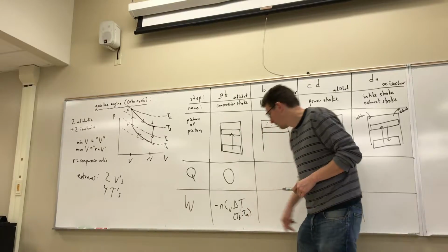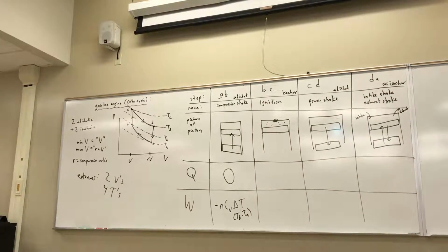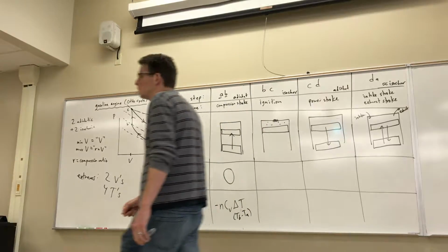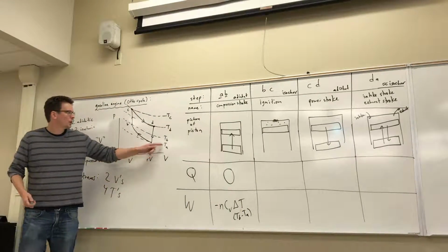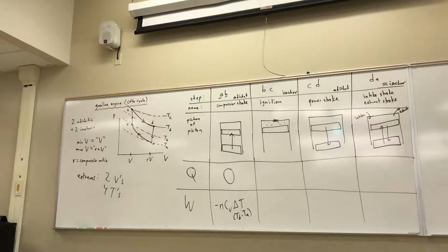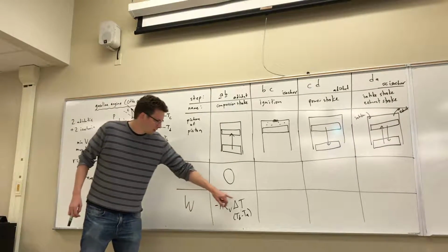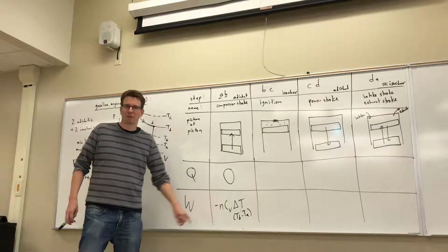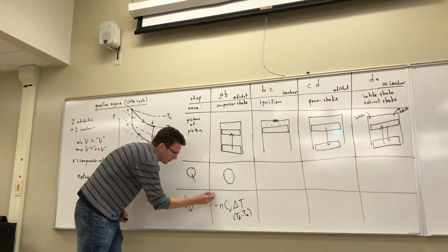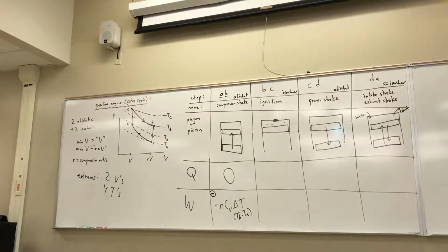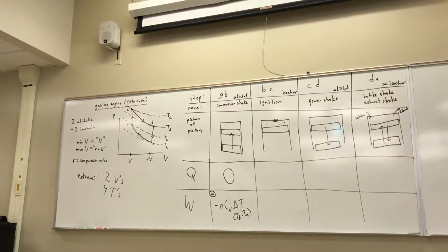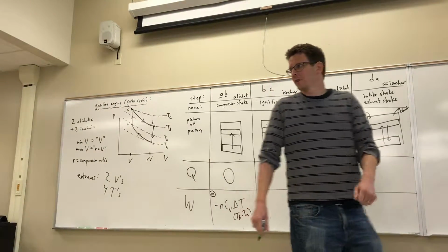That's A to B, okay? So what happened to the temperature? Did it increase or decrease? Increased. Okay, what's the sign of the work? So the delta T is positive, but the work is negative. So this is negative overall, right? I guess I'll just put the sign in the corner, right? Because it's going up, it's going in, right? We're putting energy into the gas as work, and when work goes in, that's negative. All right? Okay, let's do our other adiabatic process.